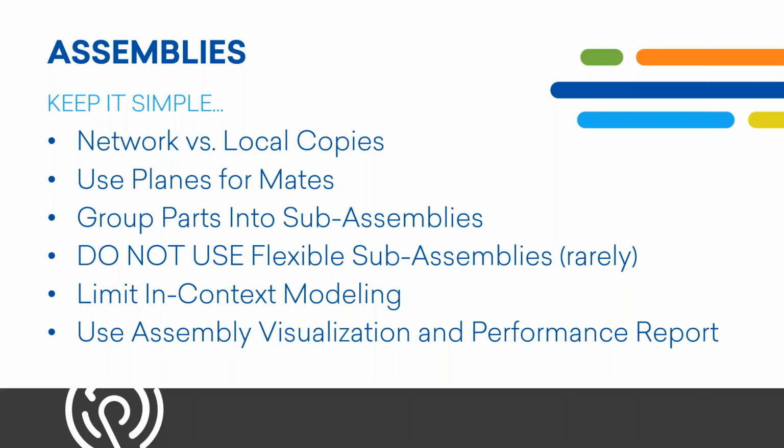If you're working inside of an assembly, we recommend, so I'll jump down to the third one, group parts into sub-assemblies. So a sub-assembly is going to come in as rigid, it almost comes in as a part. And this allows you to work with that entire group as one entity that moves together.